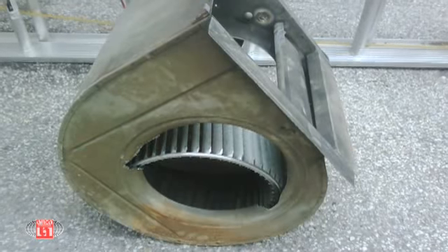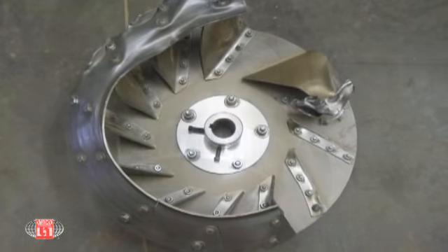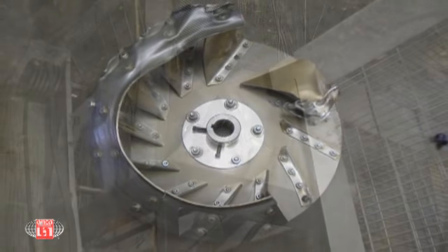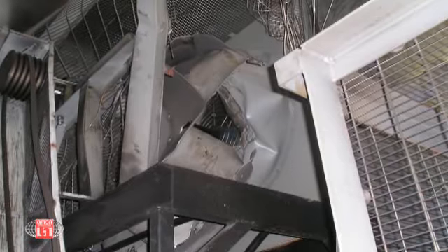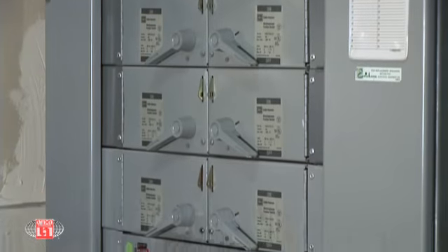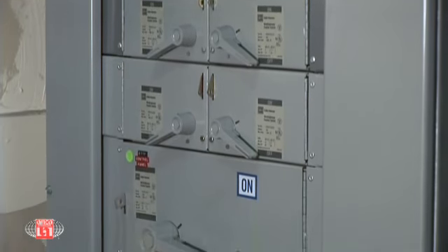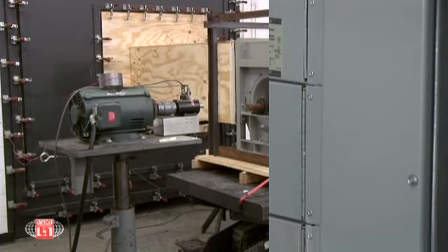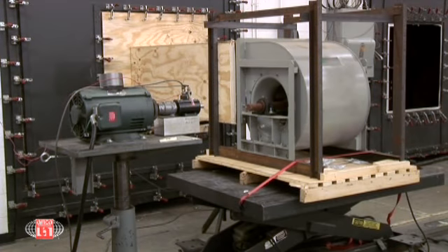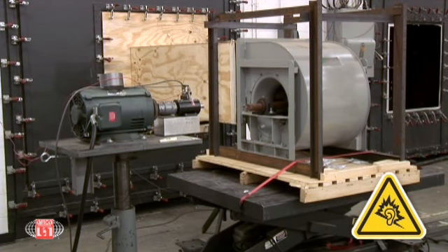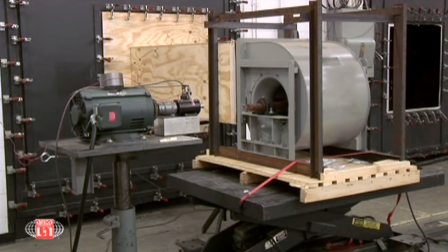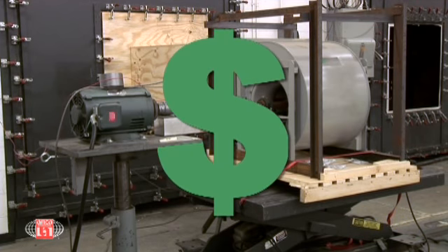Certain structural elements affected by fan speed can fail catastrophically if the maximum safe speed of the fan is exceeded. Make sure that the electrical equipment is capable of handling the increased power requirements. When fan speed is increased, you can expect both the fan and the system's fittings to be louder. Additionally, there will also be increased duct and fitting leakage.